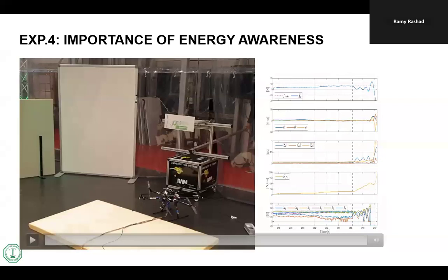First of all, it's very limiting to always make sure that I'm passive. And if you lose the passivity, for example with the variable impedance controller, you need to think of something else, okay? The environment itself, I cannot always make an assumption on, even the passivity assumption. Even if it's there, the environment can just disappear, this situation happens. And this is why you need something extra, okay? And this is the new paradigm that we introduced in our work, and it was called energy-aware impedance control.